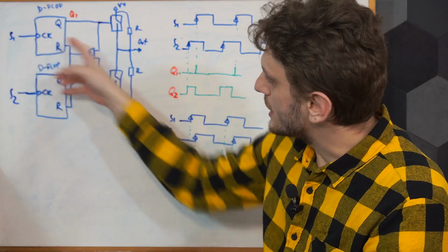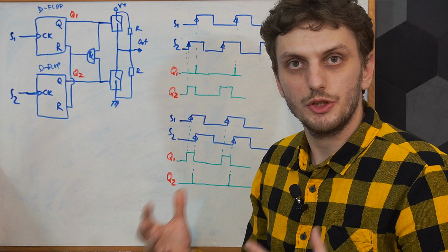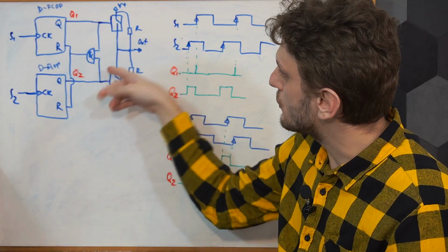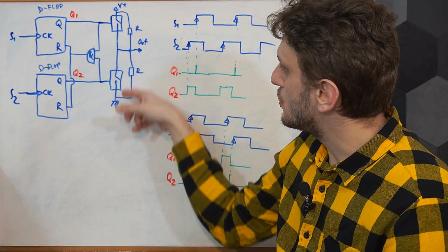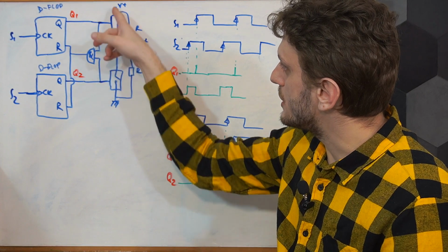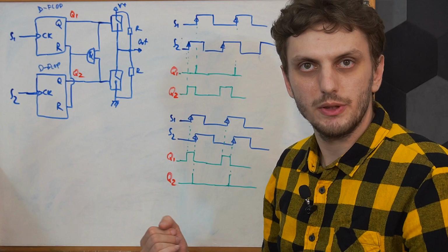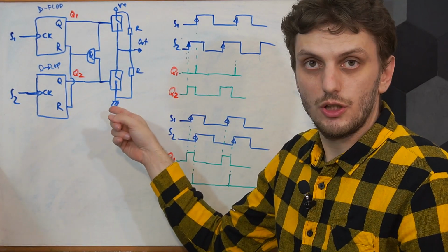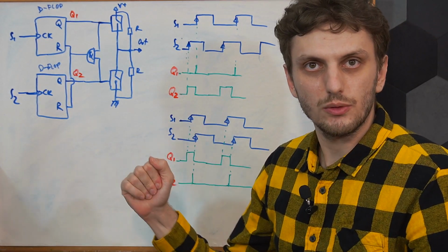First of all, our signals pass through D-type flip-flops. These are logic gates that will trigger on edges. Then the outputs of these pass through an AND gate, which resets them. But they also pass through a couple of switches, one that pulls the output high and one that pulls the output low. And now, depending on how you want to build your phase detector, you can have the output left floating when both switches are off, or add a resistor divider to set up a center voltage.